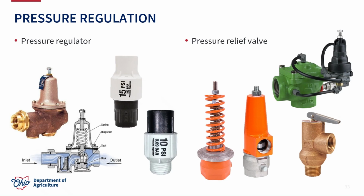Once we have that water in the system energized and pressurized, we need to have a way to be able to control that pressure, and that comes into play with a pressure regulator. So closer to the supply, we may have a regulator that's setting what that pressure is as the water is traveling through our main lines and distributing throughout the system, right? We want to be able to protect any of the components downstream from overpressurization.